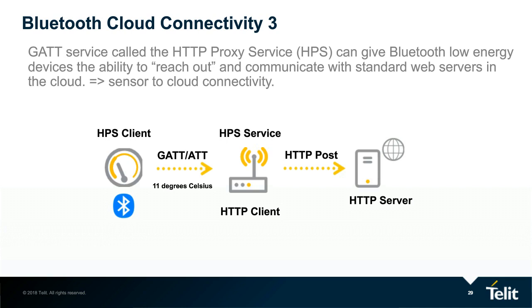The only disadvantage of this is, if you have a very simple temperature sensor, for example, which is on your window, which has no other connection, or a motion sensor, this could work, where the sensor just reaches out to the cloud when something changes. The disadvantage is there is no way to address the sensor from the cloud, since the sensor will be asleep all of the time except when something changes that it wants help with.